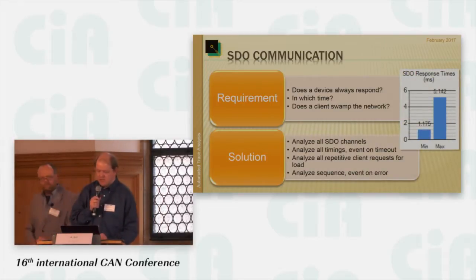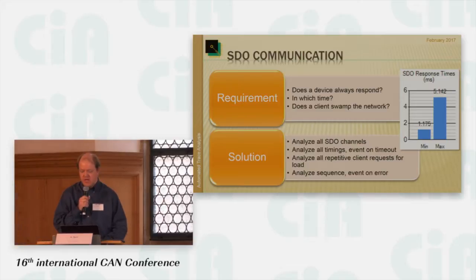The analyzer that we developed can understand the SDO protocol. This allows many aspects of the protocol's operation to be measured and checked. For a fully meshed network, or a network where nodes have multiple SDO clients, the use of each channel can be analyzed in parallel to determine the minimum, average, and maximum response times. We can quickly tell if a particular channel or node is generating the bulk of the SDO messages on an entire network by keeping running counts of the total number of requests, responses, and aborts, which might lead to potential optimizations of the nodes and the overall network design.